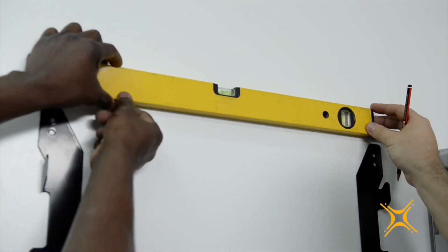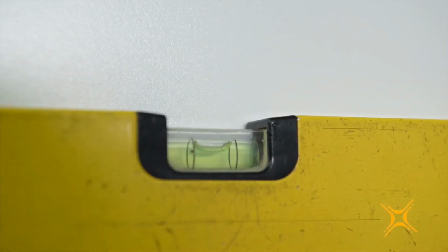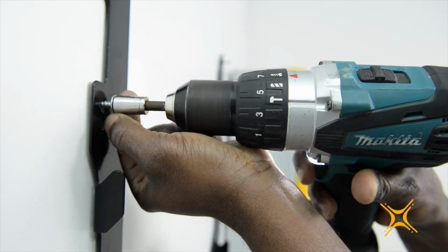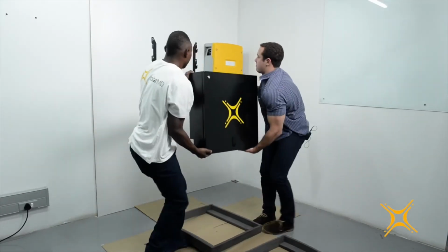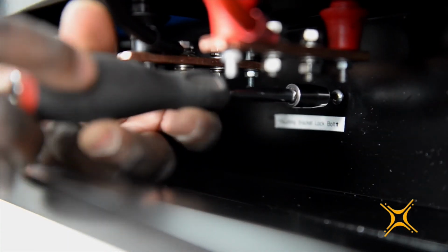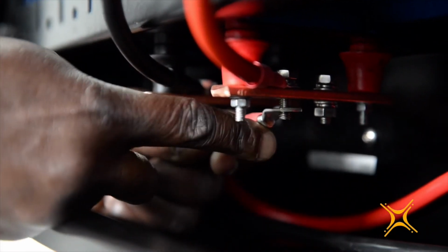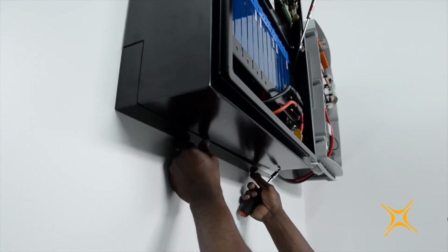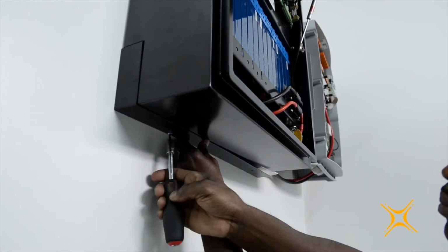The mounting bracket is the exact size of the battery's outer dimensions, making it easy to see where the battery will be positioned. It is important to make sure the mounting bracket is upright and level. Secure the battery using the mounting bracket bolt. The battery has cable entry points on both sides and offers a bus bar with 4 connection points. If only one entry is used, the other can be covered with the L plate provided.